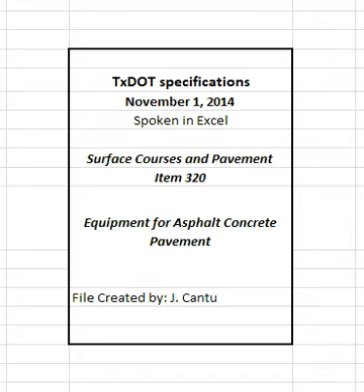Clean all truck beds before use to ensure the mixture is not contaminated. Coat the inside truck beds, when necessary, with an approved release agent from the department's MPL. 2.3 Placement and compaction equipment. Provide equipment that does not damage underlying pavement. Comply with laws and regulations concerning overweight vehicles. Use other equipment that will consistently produce satisfactory results, when approved.